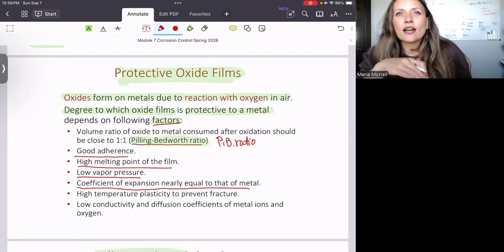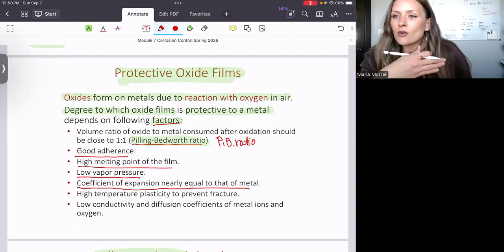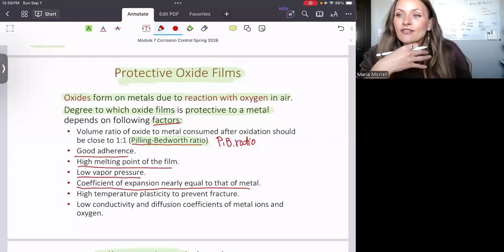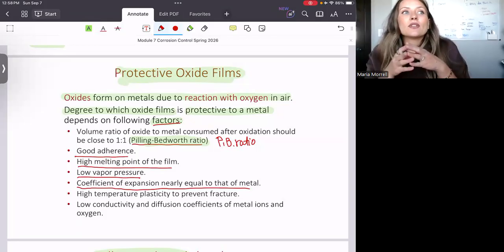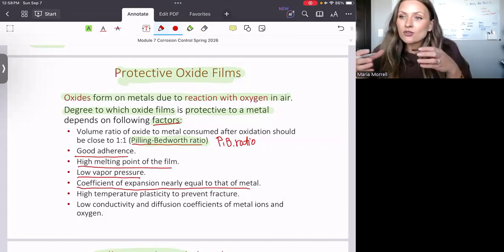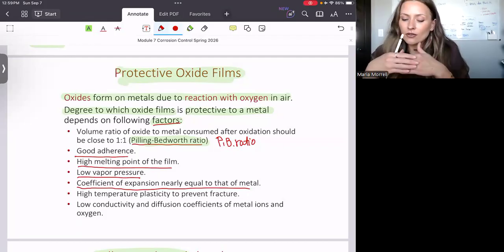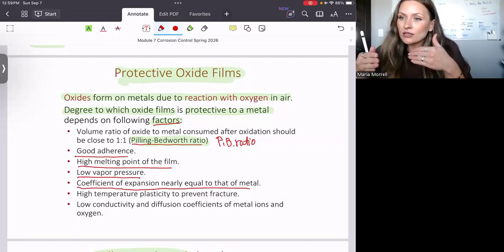50 years ago, or I actually don't really know, but there was a point in our history where people would use cement. And while cement does serve the purpose, the reason it wouldn't stay long in the tooth is because it has a very different coefficient of expansion compared to the tooth itself. And so what happens is that if the tooth expands and the cement doesn't expand to the exact same size, then there is going to be a crack or a space, a void in between the two materials that gets filled with debris, and this is how you basically lose a filling. And the moment you lose a filling, you also see that there is another cavity underneath, right?